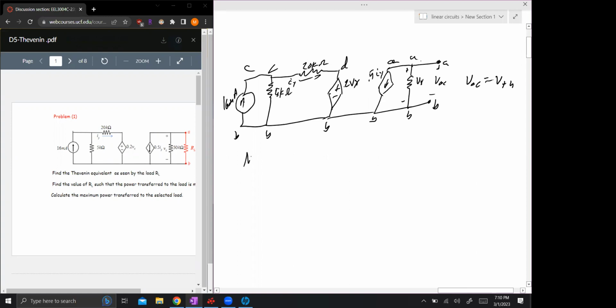So with node voltage, you're gonna need n nodes minus one equations, because one is your ground node. And with mesh current, it's just the number of loops that you have. So it looks like this is gonna be about the same, I think. Wait, one, two, three. Yeah, three. Let's do node on this one. Node looks like our best shot. With node, they always say do the easy stuff first, just so we could find our basic node voltage here.